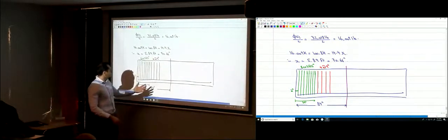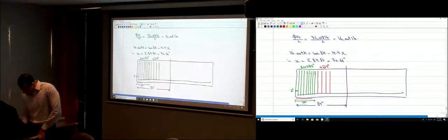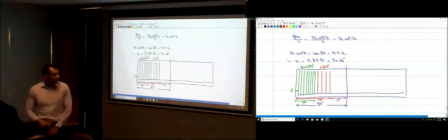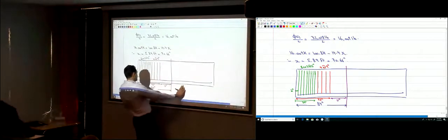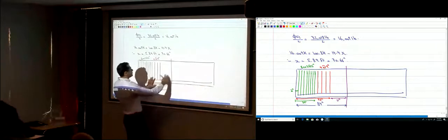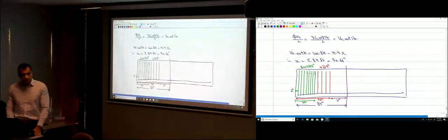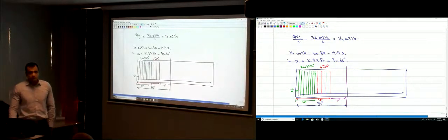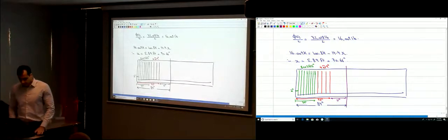This distance was what? 73, right? That is 73 inches. And then over here, I have 11 inches right in the middle with no stirrups. And definitely this is symmetric. So you'll still have another 11 inches here with no stirrups, and then this 4 number 9 bars, and then 8 at 5 inches spacing. Okay? Any question? Okay.